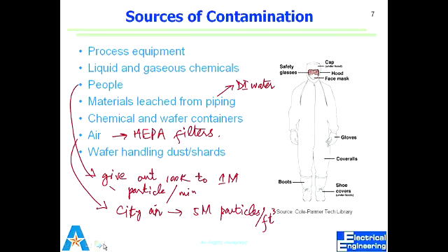And the airflow is always what we call turbulent and laminar flow. Have you guys ever heard of turbulent flow and laminar flow? Mechanical engineers, right? So what is turbulent flow? If you break down the fluid flow into lines of particles, they don't have any order, they are random. That's turbulent flow. But laminar flow is when everything flows in a straight line, so the flow is much more aligned. We always want to have laminar flow inside the clean room. So the whole air is always being pushed up, passing through HEPA filters and coming through the floor again.